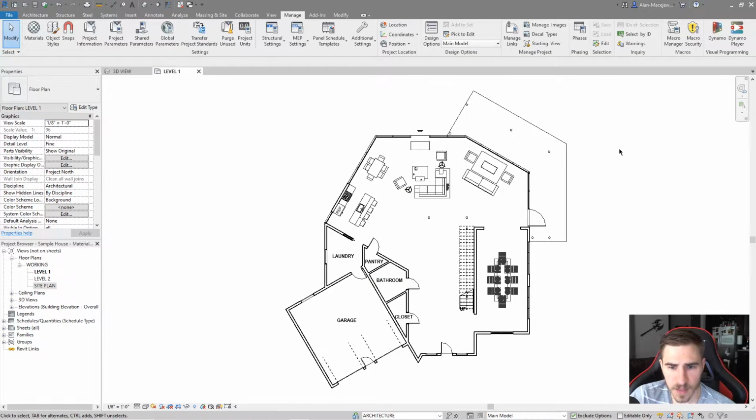That's great. So you know an element is in a design option if I can no longer hover over it and select it. Like when I take my mouse and hover over these elements, I can't select them or do anything. Even clicking and dragging, I can't do anything. And that tells me something. That tells me that they are probably in a design option. That's kind of how the design options work. And they're in a sense like a pinning of an object, but to a next level to where you can't really do anything unless you go an extra step.